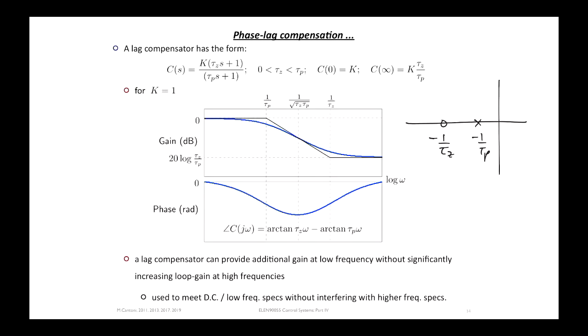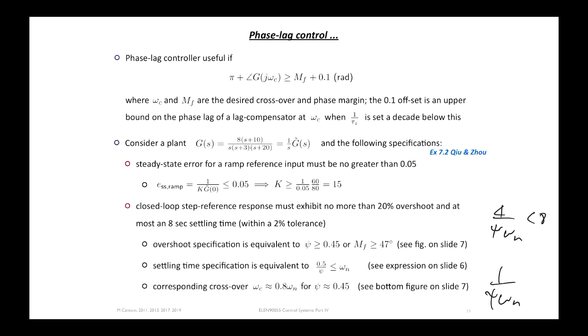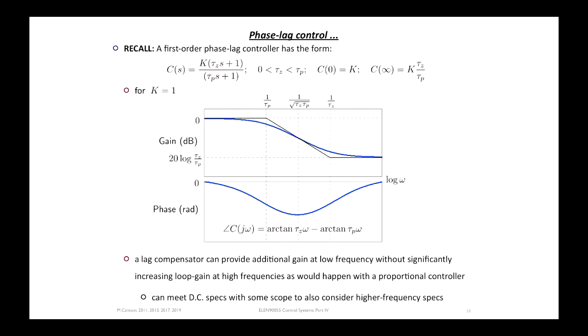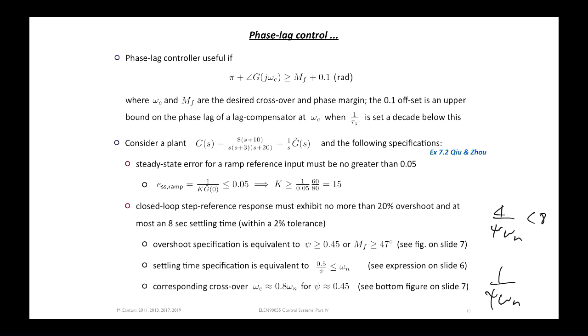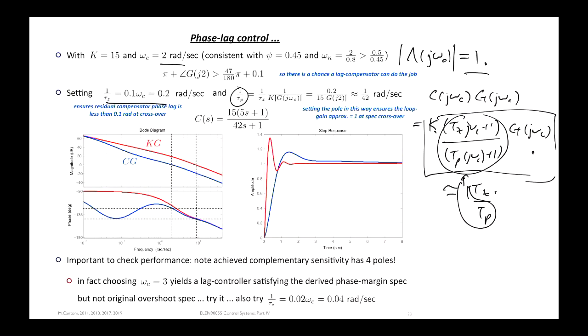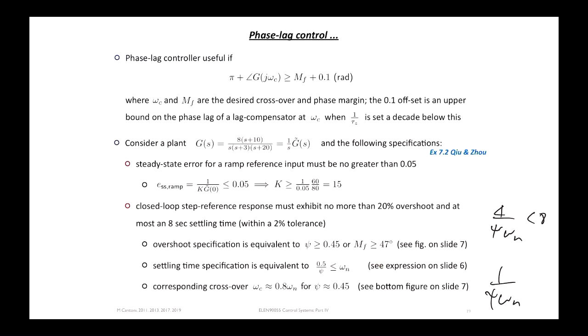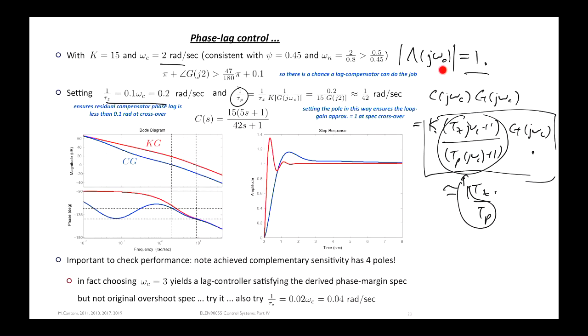What we were doing in these examples, and they really are just examples, is seeing how to determine the coefficients or the parameters of the controller by writing down relationships that they must satisfy in order to achieve desired phase margin and a particular crossover frequency. Here, for example, was just about making sure that we've chosen one of the parameters, the only one left after choosing the others, to meet these specifications, to ensure that at the desired crossover frequency, the magnitude of the open loop transfer function is equal to 1.